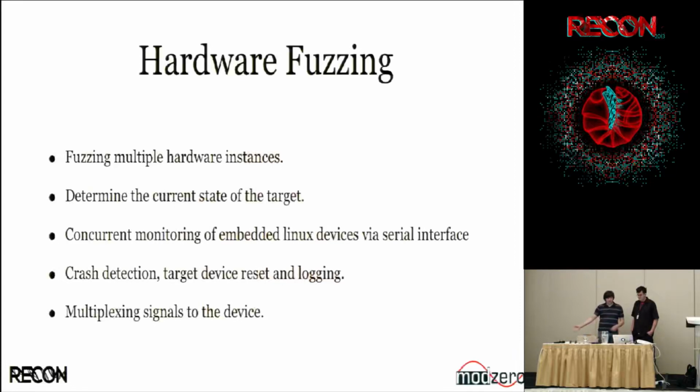Monitoring is another big thing. If you're monitoring and you see something's crashed, you can reset it with the hardware as well. That's why it's hardware. We can toggle a pin, pull it low, or have maybe a pass transistor, cut the power to this board, turn it off, and start it back up. The other important thing is logging, and we can do much better logging than if you were just to use an FTDI, for example, because in the FPGA you can implement much bigger buffers.